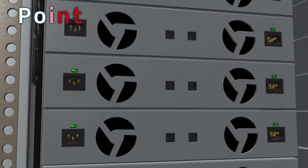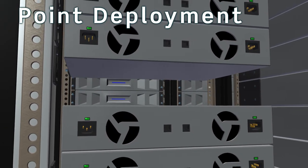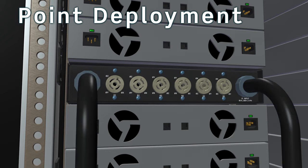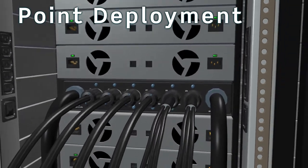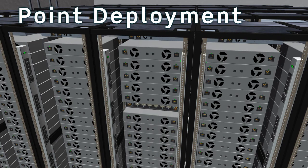The second is the point deployment method. This allows a build-as-you-go methodology, deploying Z-PDS units in selected areas of your data center, such as cabinets with high power density. First, install uniform AB three-phase receptacles in your chosen power density using your existing infrastructure of power whips or busway. Next, install Z-PDS units and connect plug adapters or Hydra plug adapters if you need them. Finally, connect your plug strips and IT equipment. You can expand your Z-PDS installation as and when you like.